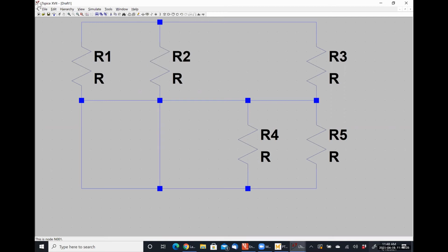There we go. Now I have my phase angle in degrees. So I have a means by which to compare the time delay between my two signals to their phase difference, all based around this relationship with omega.